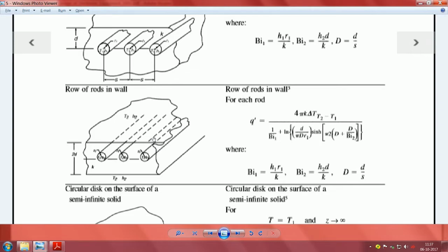So, even in the conventional old refrigerators, where you have the ice chest or the evaporator, which is on the top, which is called direct cooling, you have a box which is made out of sheet metal, and what is equivalent to these rods, that small pipes, are embedded in it. Sometimes they emboss the pattern and then the whole thing is spot welded, and then it forms a narrow channel.